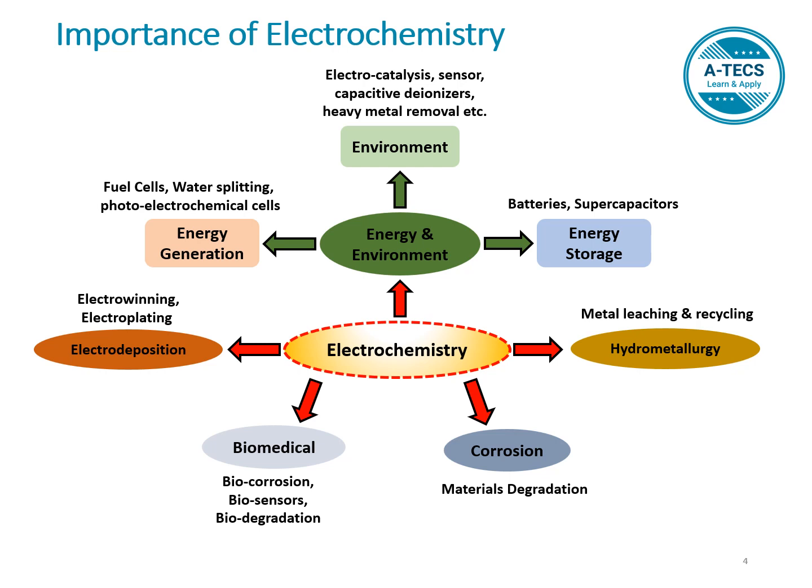On the other hand, I'm showing you a few examples from electrodeposition. One is electroplating, the other one is electrowinning. In electroplating, we intentionally deposit metallic species, which are dissolved primarily in an aqueous medium, by supplying an external amount of energy to deposit them on a metal surface. The examples are nickel and chromium plating.